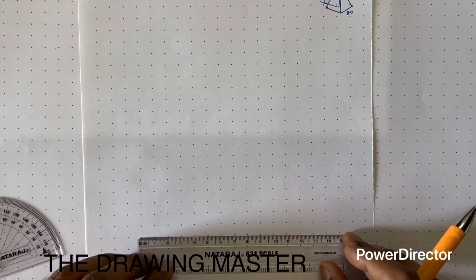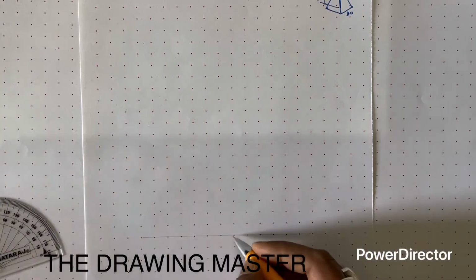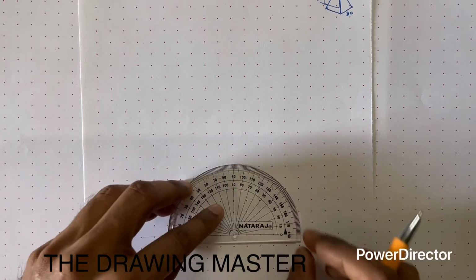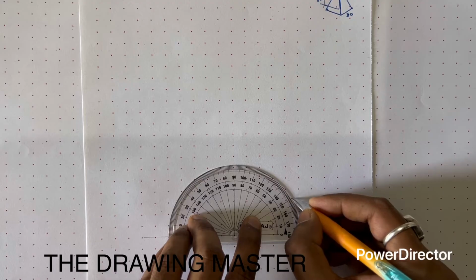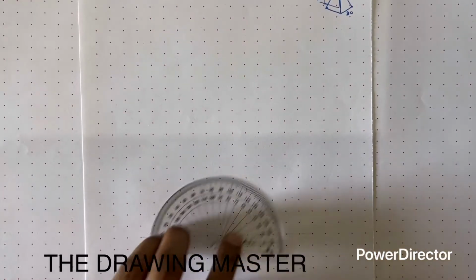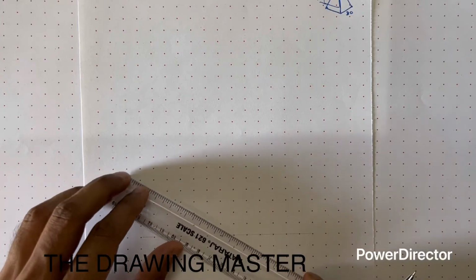Like previous drawings, first we will draw the reference line. Select one pole point. Align your protractor with this pole point and reference line, and without any second thought, just measure the angle of 30 degree both sides. See, in isometric view, always 30 degree angle will be there both sides. If you have any doubt in theory part, you can go through the theory lecture of the isometric view and isometric projection.